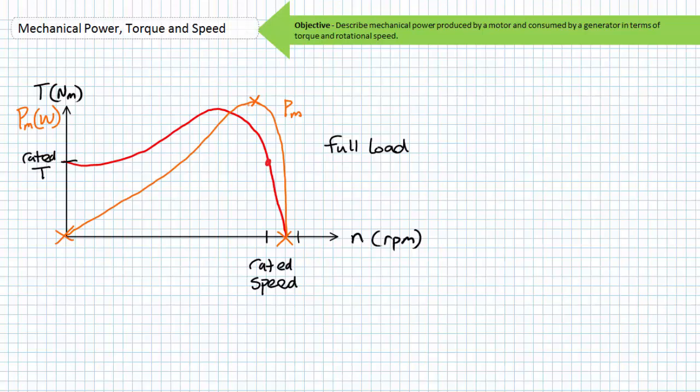If we overlay this general power curve, it might look something like this ugly approximation in orange. In addition to avoiding a stalled motor beyond breakdown torque, we're obviously operating in the linear region of the speed-torque curve for a reason. Not only are speed and torque related relatively linearly, we're trying to stay in this sweet spot in the power curve where mechanical power output is pretty high.